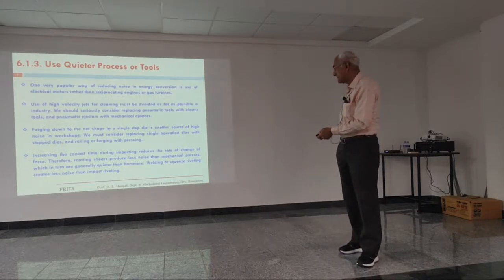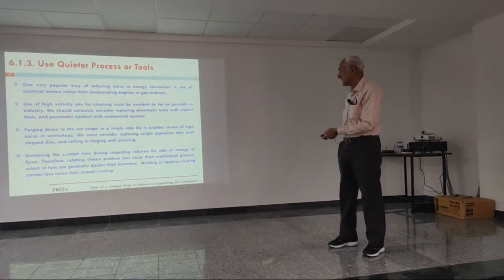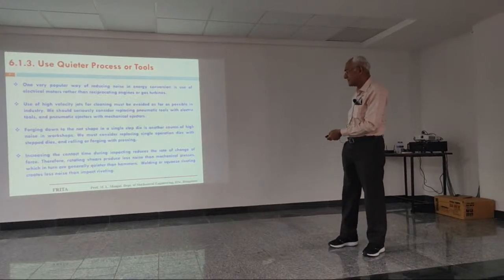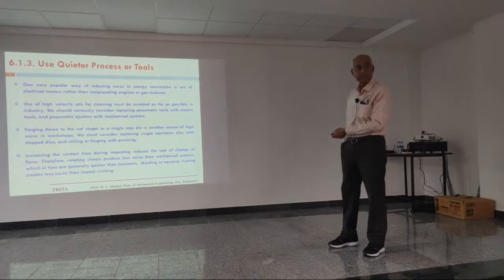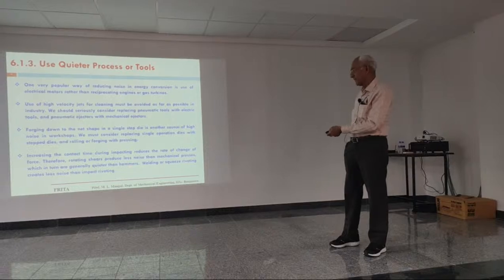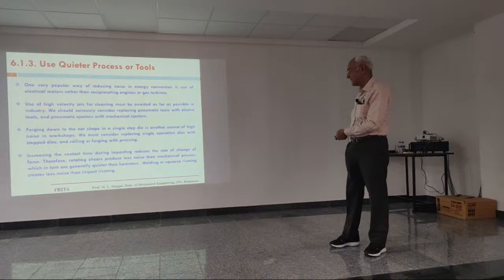Here, I am saying the rotating shears produce less noise than mechanical presses, which in turn are generally quieter than hammers, all because of this contact time. Similarly, welding or squeeze riveting creates less noise than impact riveting.